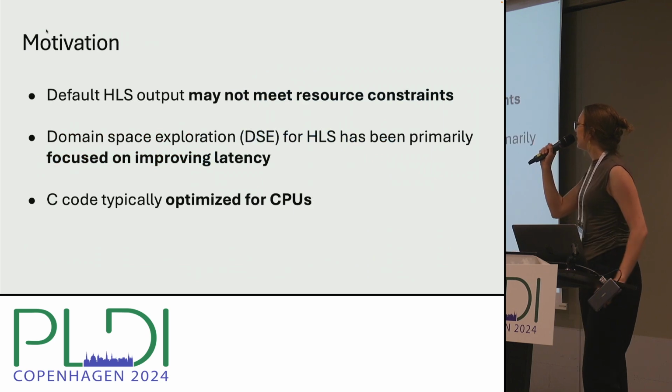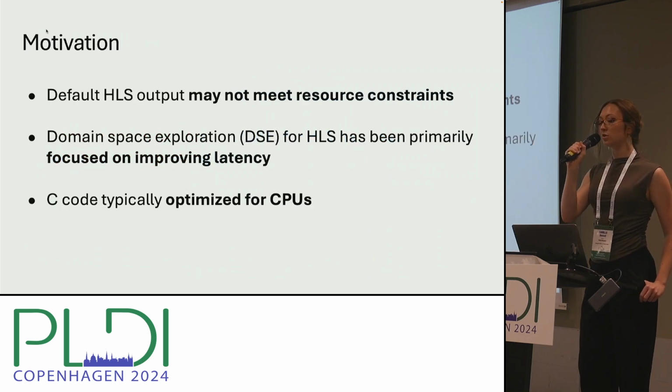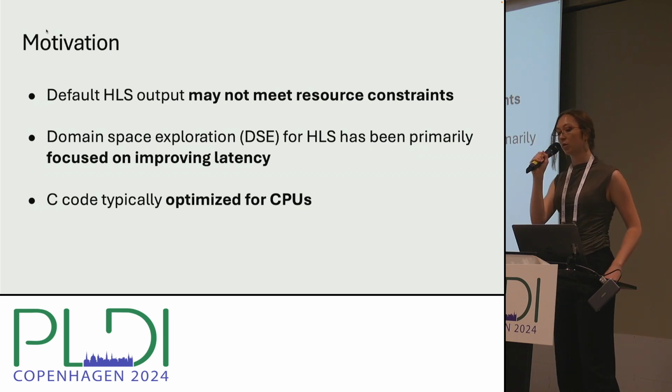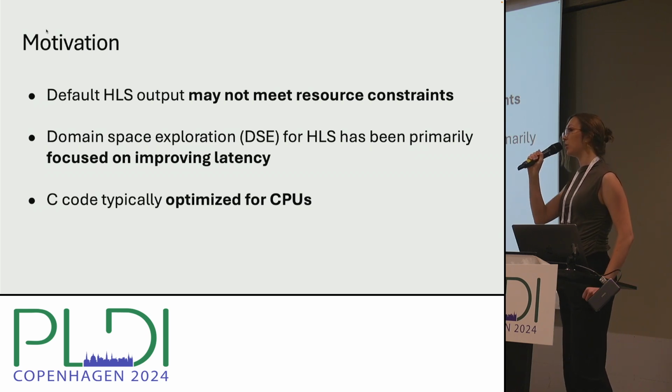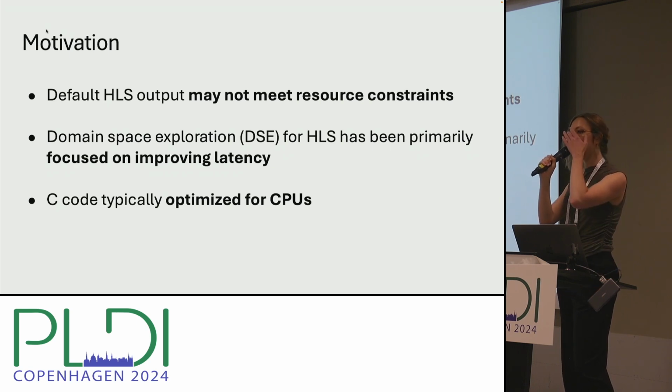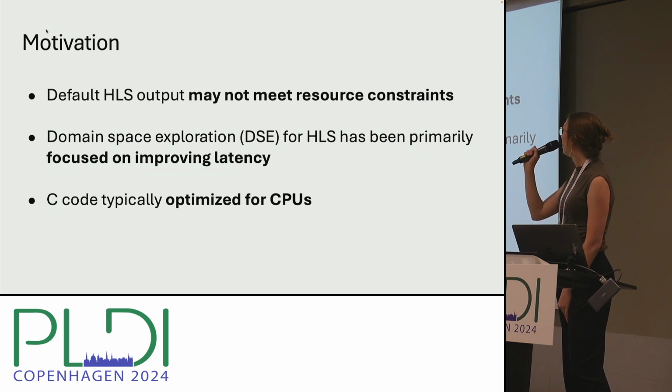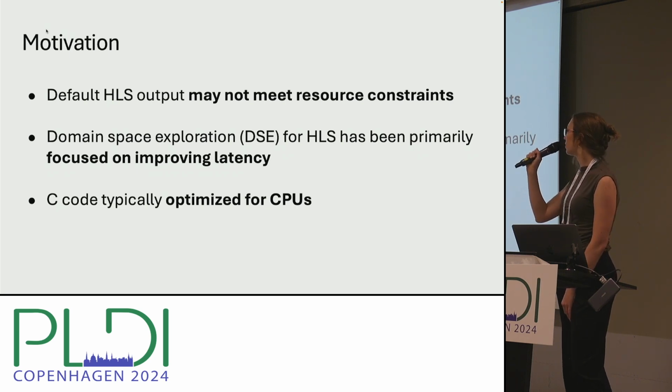All of that is to say that HLS will use your source code structure to choose what hardware format it generates, and that may be a problem if you have resource constraints. So you may be running on, let's say, an FPGA that has limited LUTs or functional units.